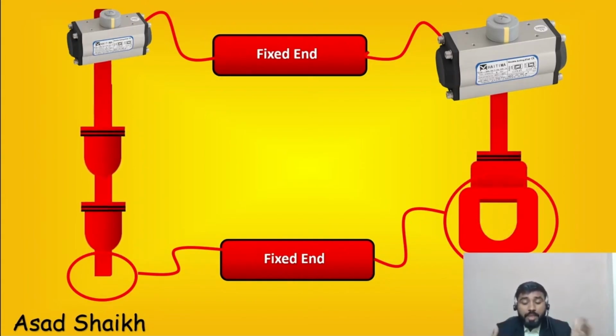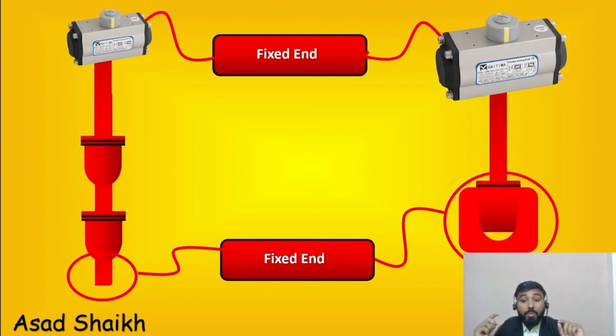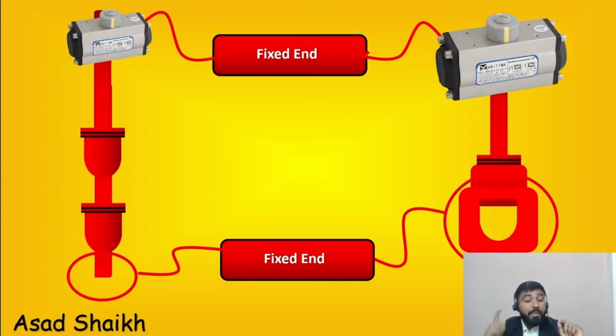Also the space requirements have reduced. So this seems to make a lot of sense. However, there is a big however. If your service has big solid particles which could get plugged into your cage, then maybe you need to still think about dual ported design.